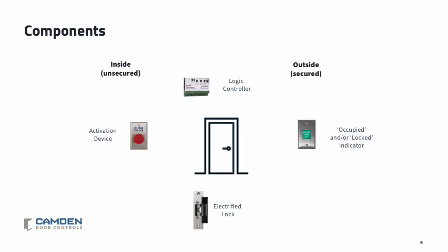Although there are a wide range of applications for privacy systems, they typically use the same basic components in a common system architecture. We start with a metal or wood door with a lock set. Typically, the system will use a storeroom lock that requires a key to open the lock set from outside, but allows free egress by room occupants to exit at any time.